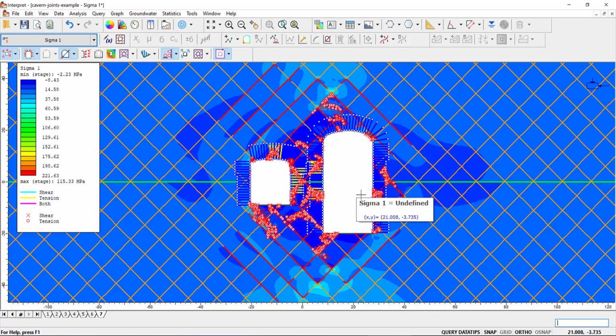Great, so now what? How does this look? We've got some yielded elements, so there's some failure going on in the material. Generally, the yielded elements are concentrated near joints, and we have some but not all of the bolt elements yielding.